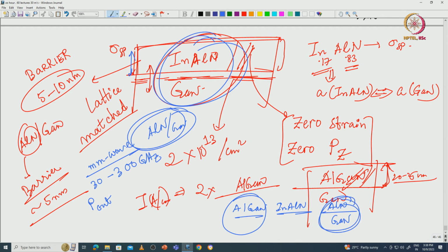However, AlN GaN and indium aluminum nitride GaN are for very high frequencies like millimeter wave, and they have very high strategic or military importance. So, even if people have the know-how or the technology for AlN GaN or indium aluminum nitride GaN HEMTs, those will most likely not be commercially available. For instance, in United States military radar programs, it is possible that they will have aluminum nitride or indium aluminum nitride highly scaled W band devices. W band is 94 gigahertz, for instance, which would not be available for commercial procurement, and the details also will not be available on the internet or to the public.